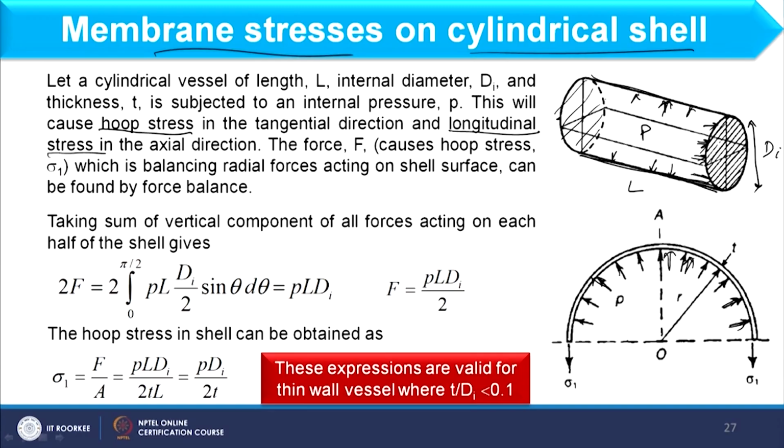So, what happens when it expands, it will create stress in this direction, okay. When pressure is applied to this, it will give stress in this direction. It means this is basically the circumferential stress. If I am considering a circular shape, the pressure will act upward as well as downward, so it will try to expand this. Whenever failure occurs, it will fail from this side. So all these stresses will create circumferential stress, and we also call this tangential stress as well as hoop stress, okay. I hope you have understood what hoop stress is, that is basically the circumferential stress, okay.